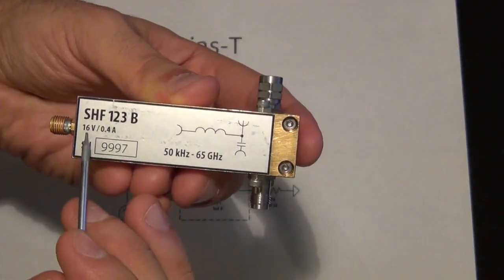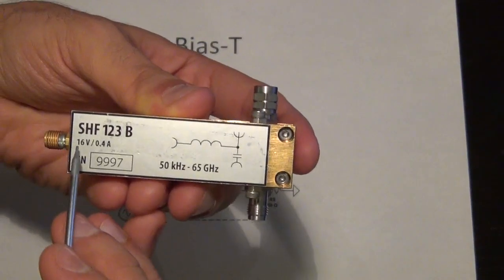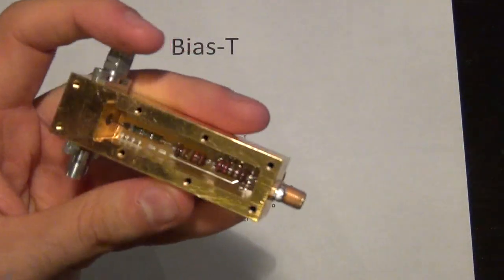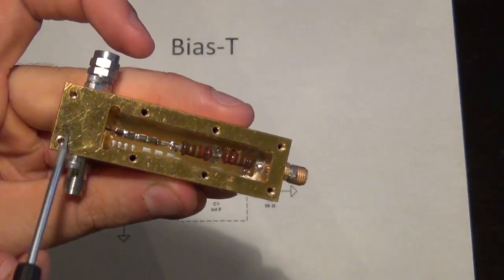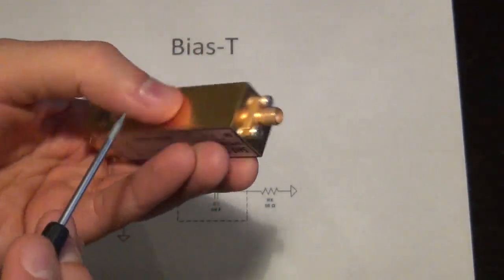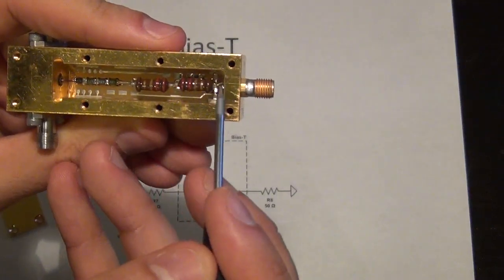And you can see it says that you can put as much as 16 volts and 0.4 amps through it. If you put more than 16 volts in here, you will break this capacitor, and if you put more than 0.4 amps, you're going to break the inductor. So you have to be very careful. If I were to open this, we can take a look inside, and you can see exactly what I was talking about. The decoupling cap is actually in here, so we can't see it. It's built in here. I don't want to open that part, but there's a decoupling cap in there. There's an AC cap, which would be this cap right here. Now there is a series of inductors that are getting progressively larger and larger.